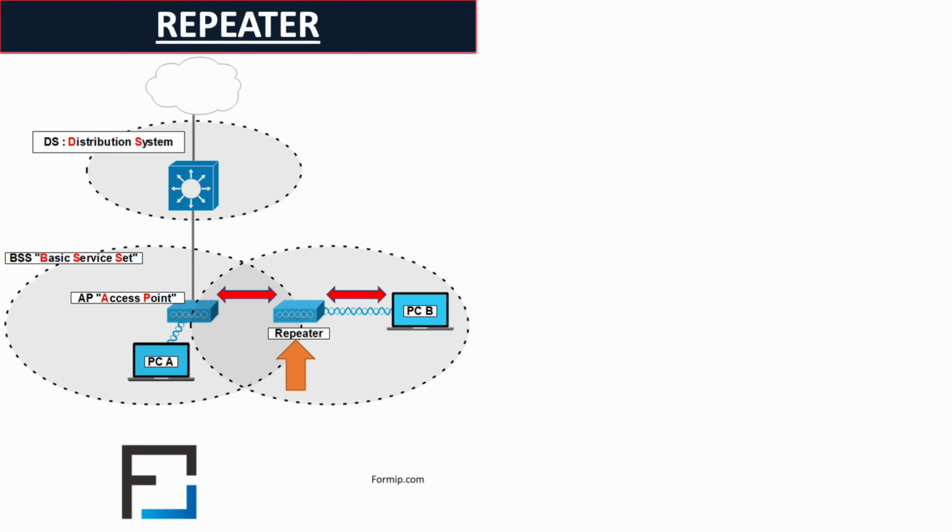To avoid this problem, it is necessary to use a repeater that can use 2 transmitters and 2 receivers in order to isolate the signals of the AP and those of the repeater on 2 different channels. In this case, one transceiver pair is dedicated to signals in the AP area, and the other pair is dedicated to signals in the repeater area.